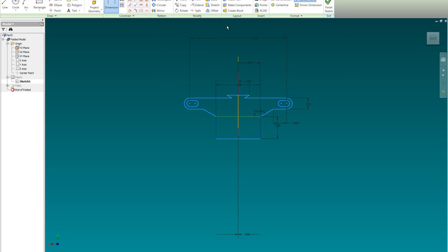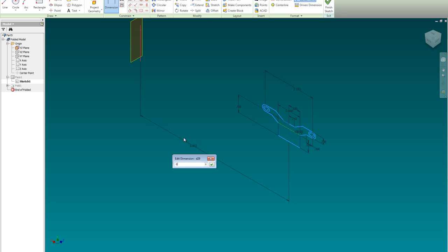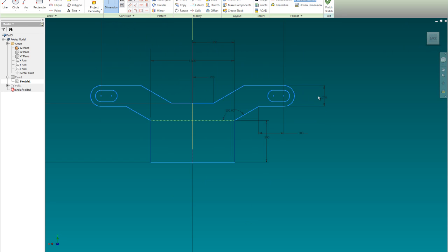Oh, that's not right. So we're going to undo and undo. Then we've got to get back over to here. It looks like I need to constrain the height of this line here from that bottom. So I'm going to do a constraint here. Again, I don't care what the number is, I just want to constrain the geometry. Then I'm going to reach down here and pick this, and go 0. And there we go. If I'm lucky, there is all our geometry in one place.